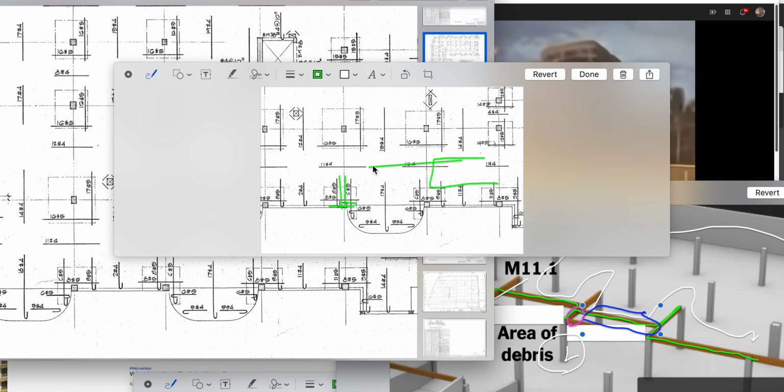It doesn't appear to be 2 layers of steel that's really engaged beyond that, all the way across over to here. It's over here, it is overlapping, but we don't get there. We need to tie it into the columns. All this is just freestanding until you tie it into the columns, until you lock it in.